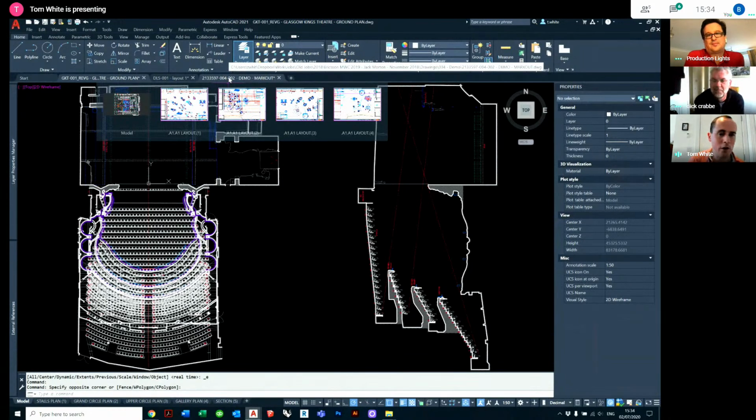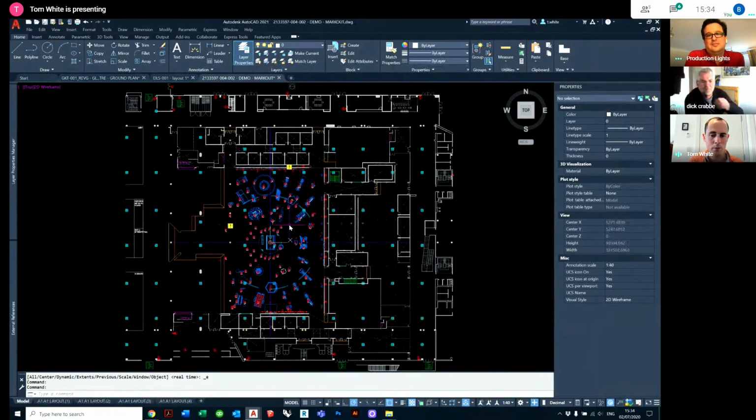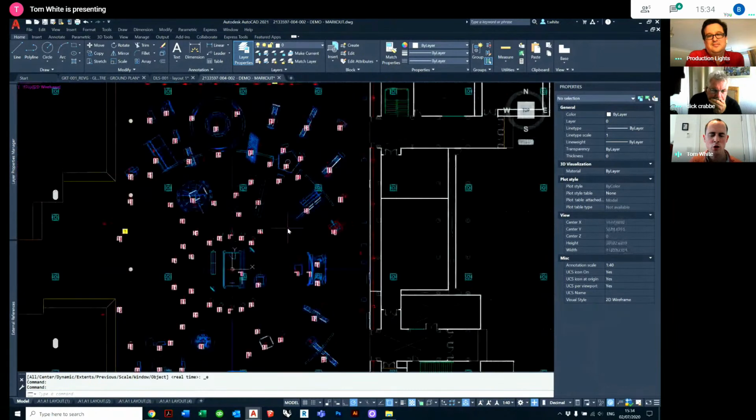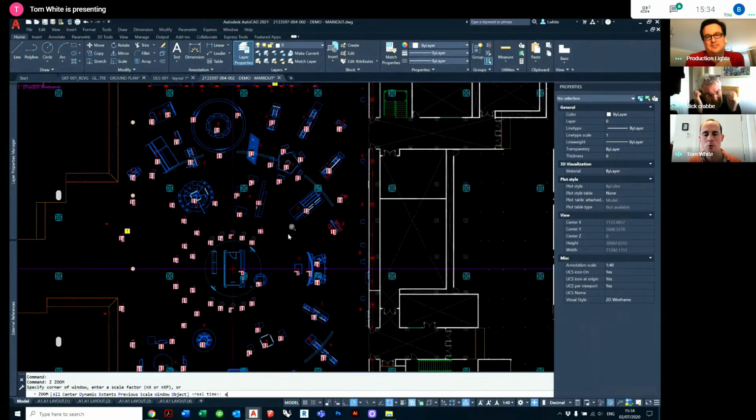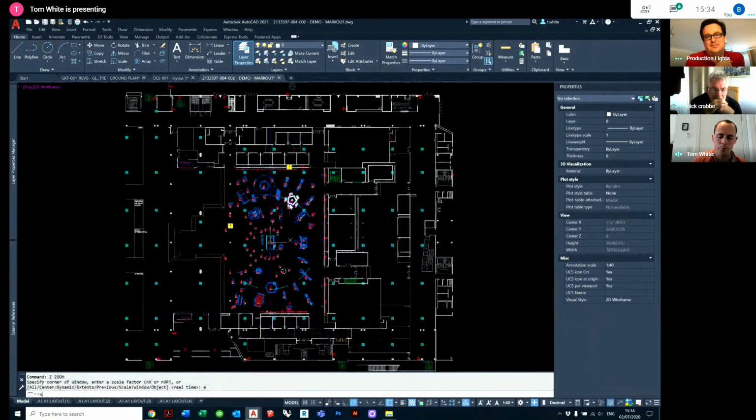So sorry, that was just going back one step. I was trying to figure out, while Don was explaining his brilliant data extraction, how I would describe regen. One regen situation, which people might have come across, is you're zooming in and out of the drawing and you get to the point where AutoCAD just won't physically let you zoom out anymore. Unfortunately, I can't make it happen right now. But basically, it's saying I don't have enough computer power, so I'm going to prevent you zooming out to focus my computer power on what you're seeing. One way of overcoming that, other than doing Z enter E enter to zoom extents of the whole drawing, is you can type regen. So regen is regenerating the drawing.